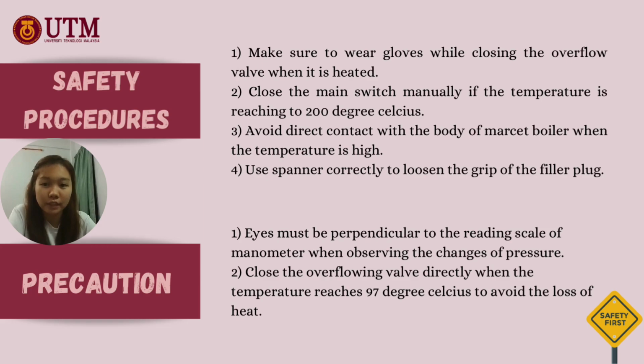So these are the safety procedures and precautions. For the safety procedures, firstly, make sure to wear gloves while closing the overflow valve when it is heated. Secondly, close the main switch manually if the temperature is reaching 200 degrees Celsius. Third, avoid direct contact with the body of the Marcet boiler when the temperature is high. The last one, use the spanner correctly to loosen the grip of the filter plug.